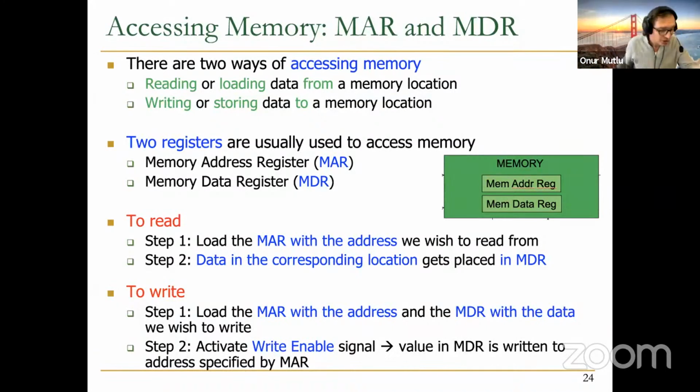time so that after you put in the memory address, at the beginning of the clock cycle, and after you assert the write enable, hopefully at the beginning of the clock cycle again, you wait enough time and the data appears at the end if you're doing a read. And for doing a write, essentially, you need to do the same thing. You need to wait enough time.